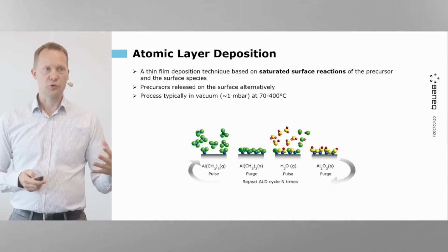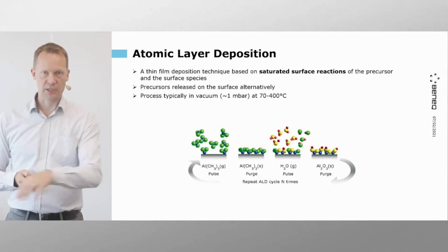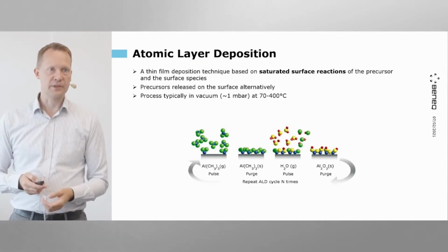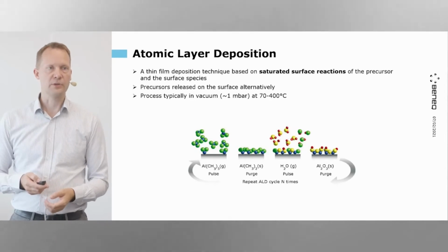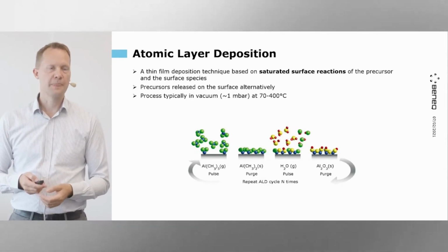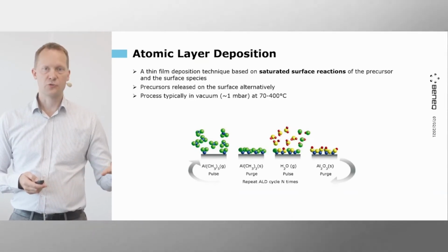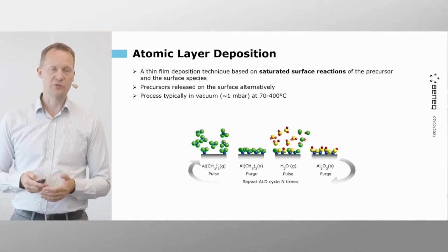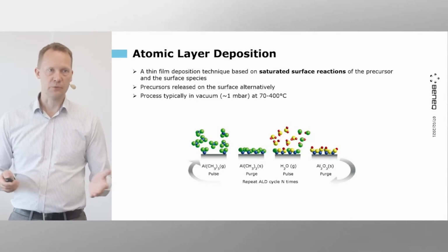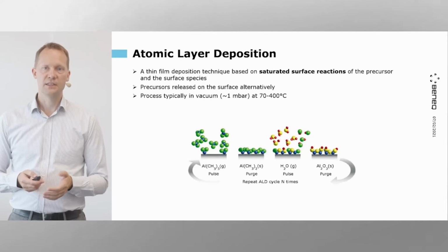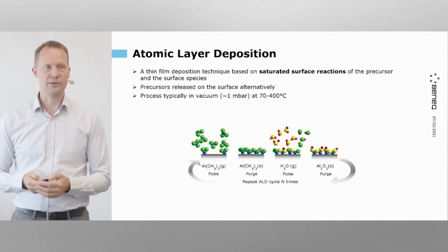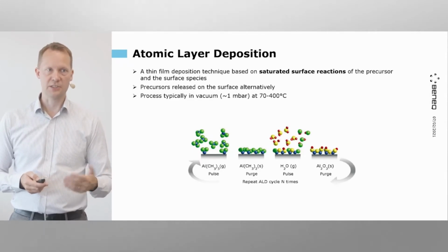So that water vapor comes in and reacts again on the surface. Byproducts are generated, and they are gaseous. They go away with the inert gas flow. And again, the reaction will continue as long as there are active sites available. Once completed, growth stops automatically, and we have completed one monolayer of the material that we are depositing, so one ALD cycle.